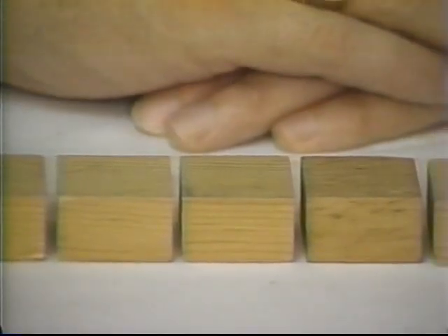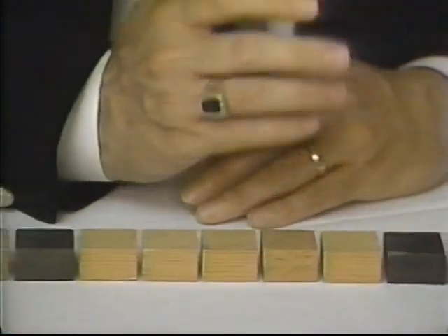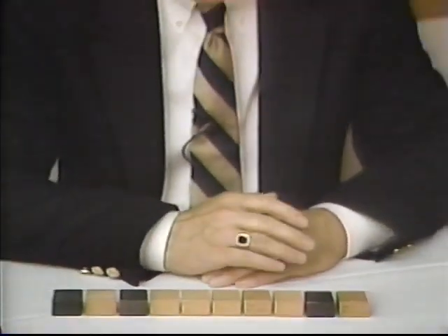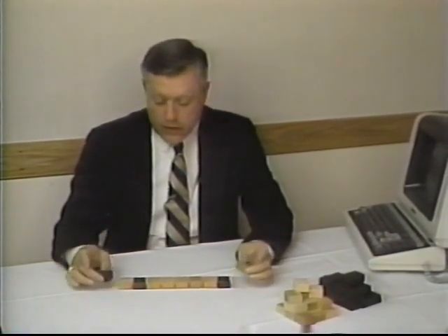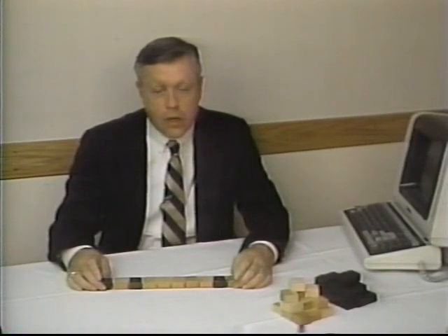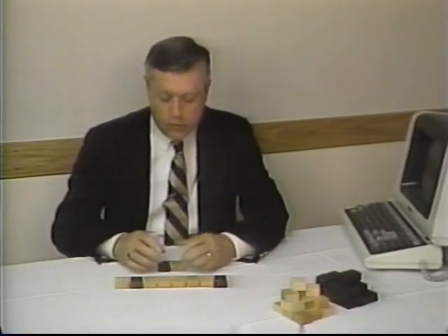As the protocols become more and more complex, the amount of time we spend transmitting the data becomes critical. Here, we're looking at the character A in the ASCII code as it would be sent down the line asynchronously. Now, if we look at this, we have a start and a stop bit to tell us where the character begins and ends. This makes a 10-bit character. Now, using a 1200 bit per second modem, it means we can only send 120 characters per second. If we could eliminate these 2 bits and make it an 8-bit character and send just the data without start and stop, we could send 150 characters in 1 second.